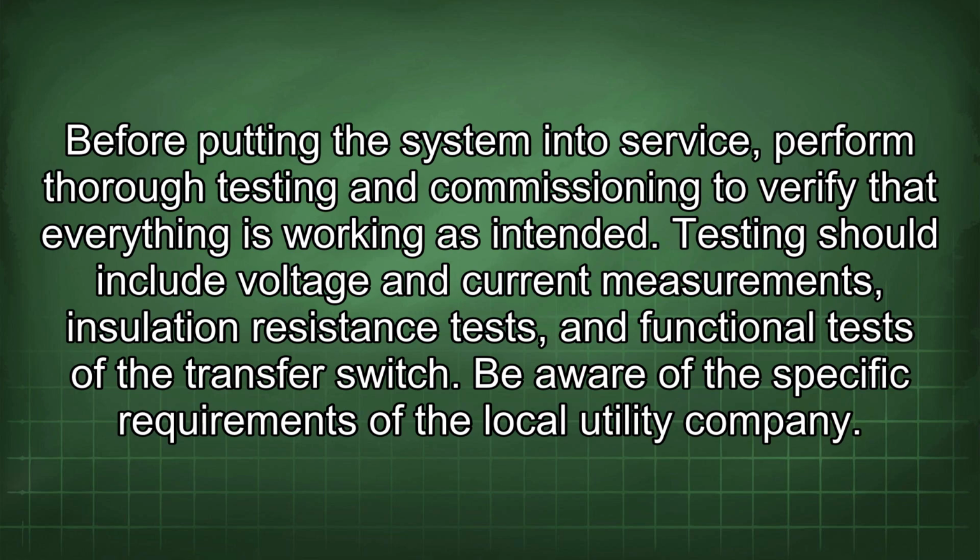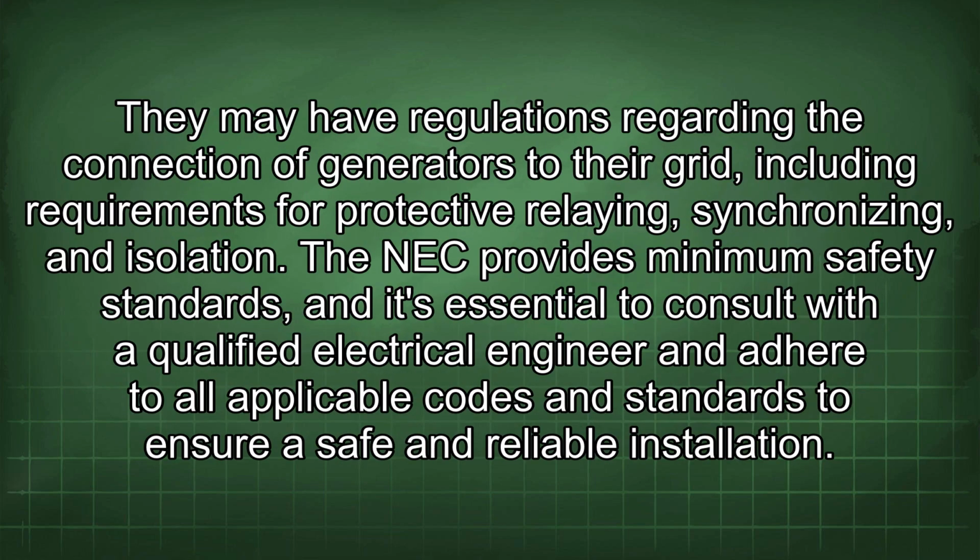Be aware of the specific requirements of the local utility company. They may have regulations regarding the connection of generators to their grid, including requirements for protective relaying, synchronizing, and isolation. The NEC provides minimum safety standards, and it's essential to consult with a qualified electrical engineer and adhere to all applicable codes and standards to ensure safe and reliable installation.